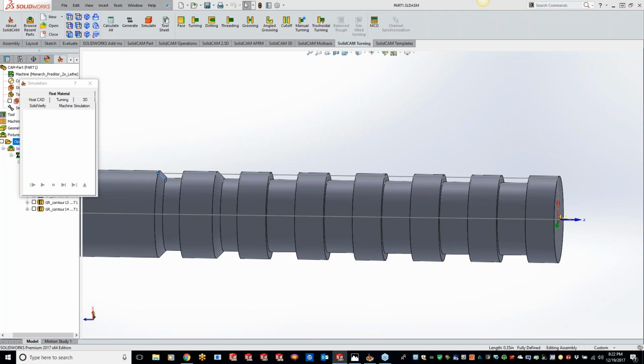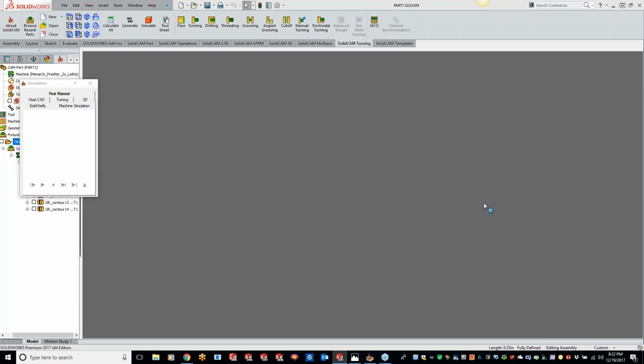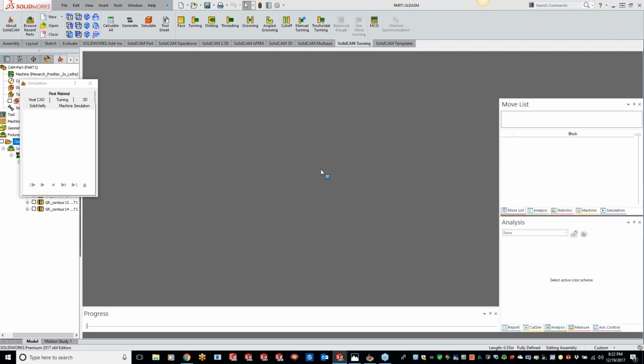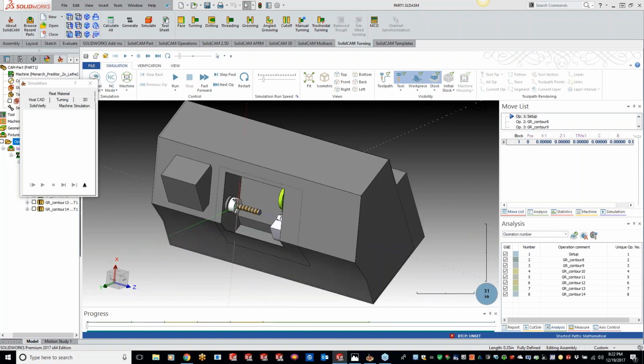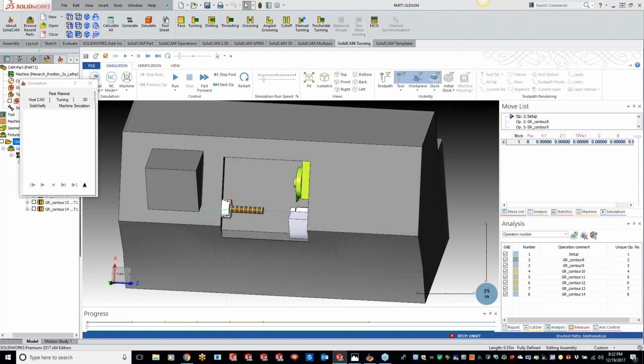Kev, quick question too on even turning. If all those slots, the first 4 that you did, were similar, could you do a transform, program one, and just apply it to the others? Yeah, absolutely. If you have multiples going along there, there's no point in programming that multiple times at all. It's just a way to cut down on programming time if the grooves are similar. Just program one and use our transform function, and boom, knock the rest of them out.